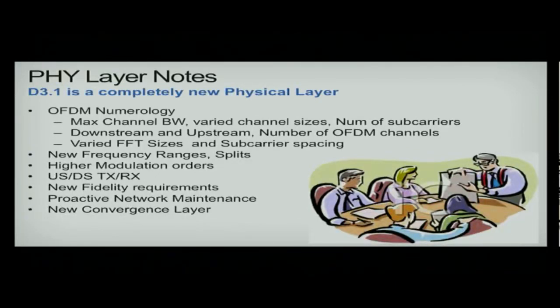It has more than about 100 contributing engineers from all the vendor companies. There has been a lot of analysis and discussion, trying to figure out what exact parameters we want to choose for the new DOCSIS 3.1 specification. Decisions have been made on what channel bandwidths we'll support, how many subcarriers would be in each of those, what the varied FFT sizes are, what the frequency ranges are, where the splits are going to be, and what modulation orders are supported.